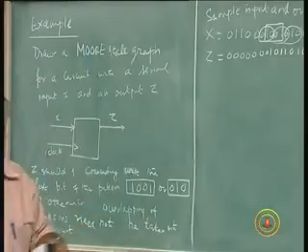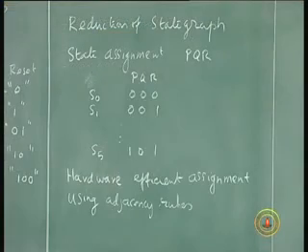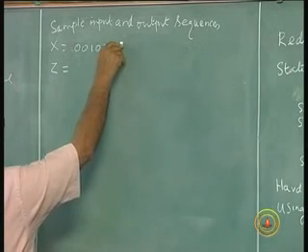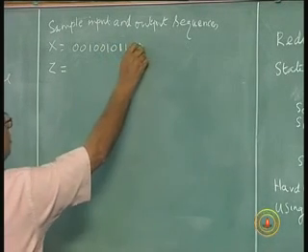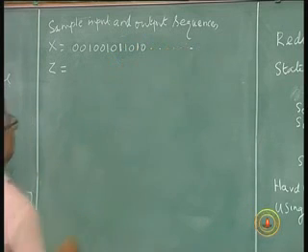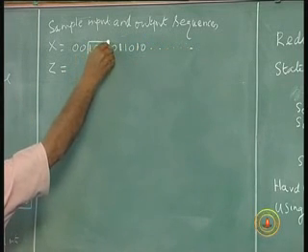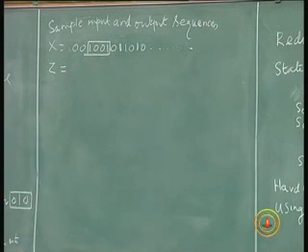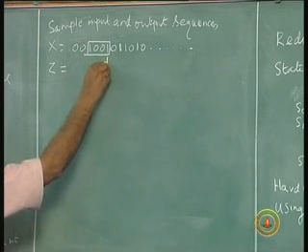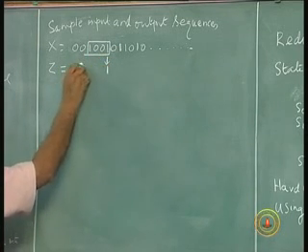Is the problem clear? So now if you want to use the same sequence, as an example, now 1001 is identified here, but the 010 I will not recognize as a part of a pattern because it is non-overlapping. So this 1001 will produce an output of 1. Until then the output will be 0.